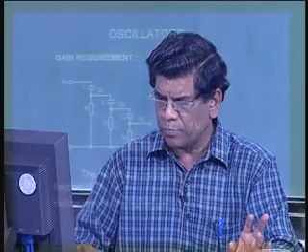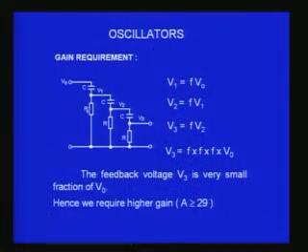Ideally it is like that, but in the actual case it is not, because the potential divider is between the C and this R, that is what you assume. That will be true only if you do not take into account the effect of the presence of the other RC networks, because they are all connected in parallel.